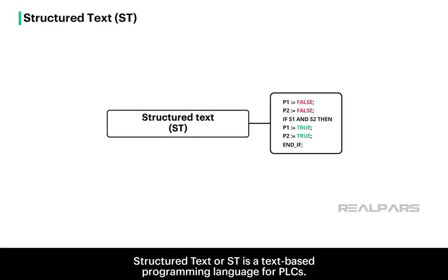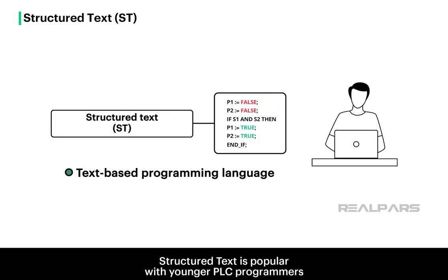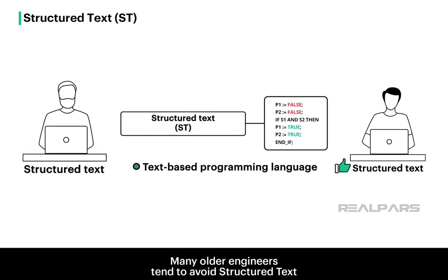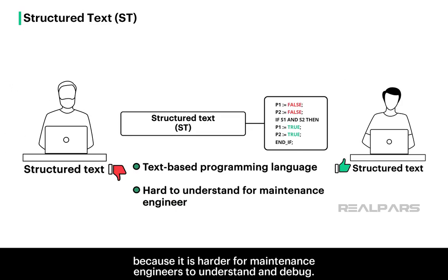Structured text, or ST, is a text-based programming language for PLCs. Structured text is popular with younger PLC programmers who are comfortable with text-based programming languages like Python. Many older engineers tend to avoid structured text because it's harder for maintenance engineers to understand and debug.